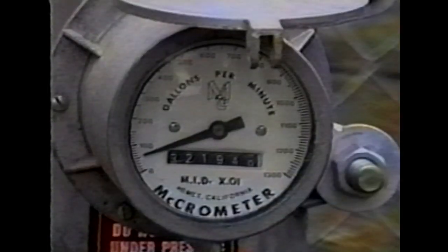Pressure gauges should be installed on both sides of the media tanks. As the media tanks get dirty, the pressure differential across the tanks builds up. Flow meters should be installed downstream of the media tanks, but upstream of any acid injection point.